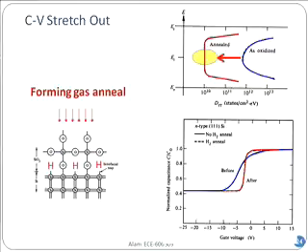All right. Now, this blue curve corresponds to that very high defect density, 10 to the power 12, let's say. After you anneal, the effectiveness is reflected by the much sharper CV characteristics. You can see it remains flat for more regions.